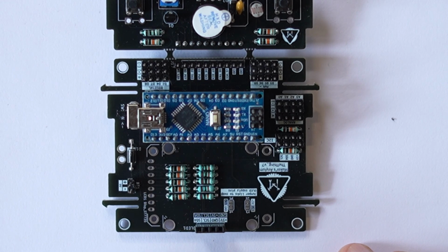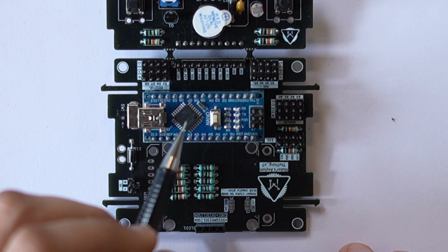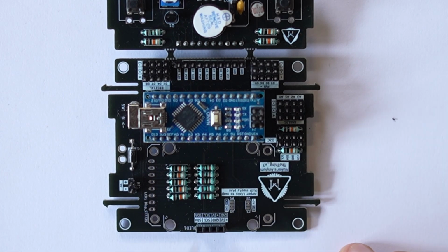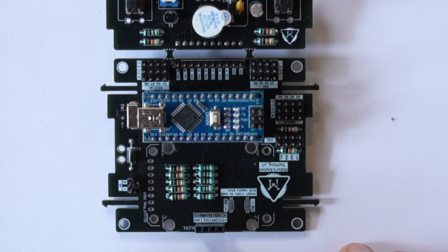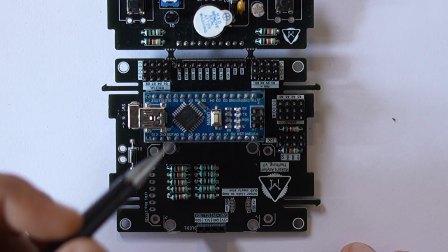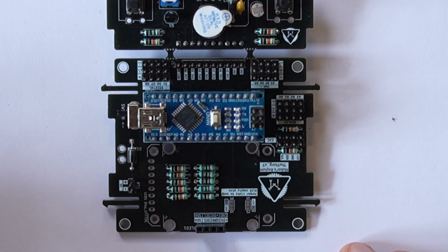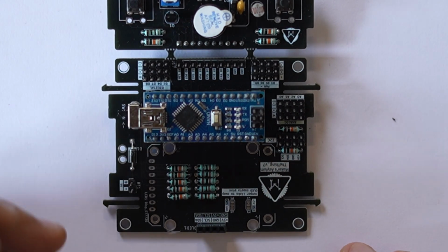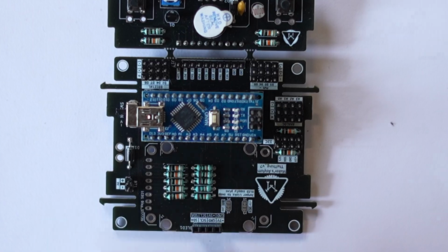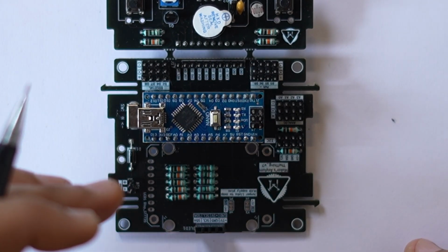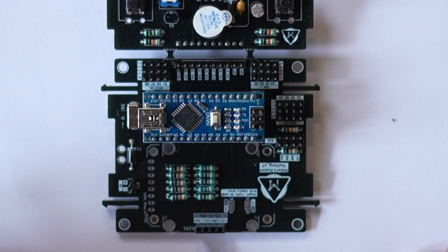It's also interesting to note that this is the Atmega chip on your Arduino Nano, and inside it, on every GPIO pin, you have lots and lots of diodes. These are known as parasitic diodes, and they basically connect each GPIO pin to the positive rail and to ground, and these are formed out of the production process that is used, and in a way they help protect the digital pin to some extent, for sure.